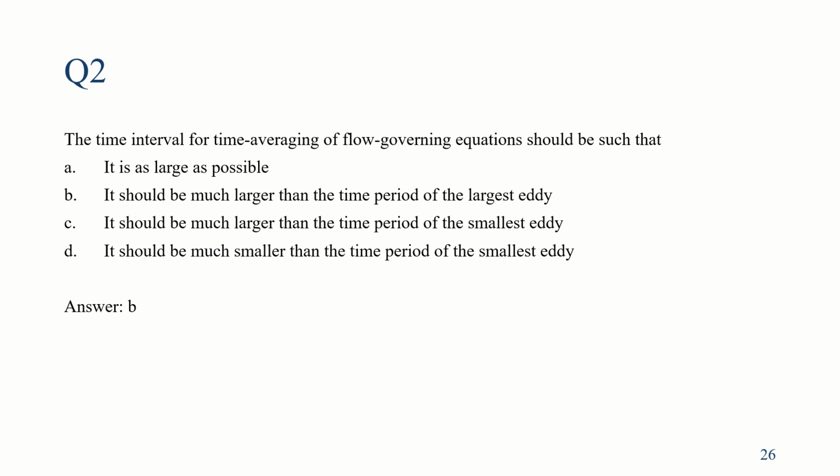Or I can say that we do not mainly want to focus on the first particle that is entering from inlet, the time it is taking to reach the outlet, that period we do not want for time averaging. Similarly, the last molecule that is going from inlet to outlet, that time period also we do not want, because before the first particle is moving, there is nothing inside the system, so time averaging would give us a wrong value.